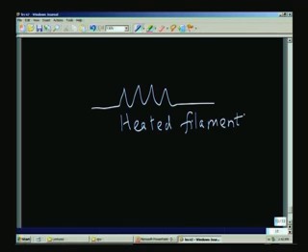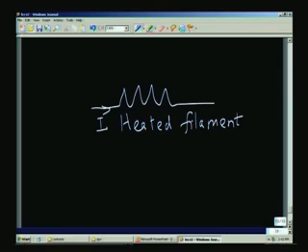Actually, we have come across this thermal detection earlier when we were talking about pressure transducers and so on. We have already discussed some of these issues, but just to recapitulate, I am looking at it again. So, I have a heated filament, that means I am passing a current through it, and now I make the gas flow across it.